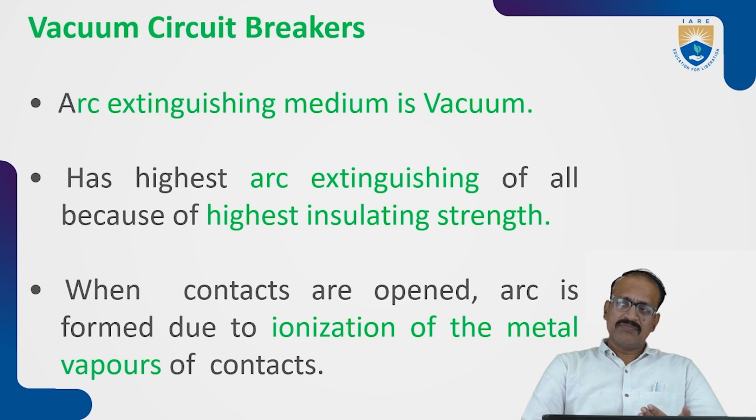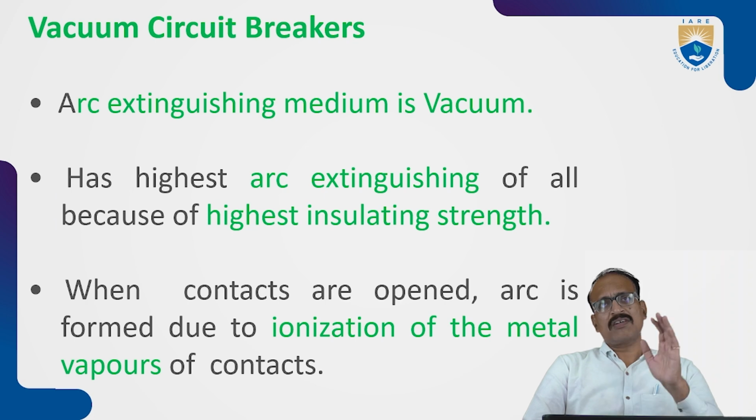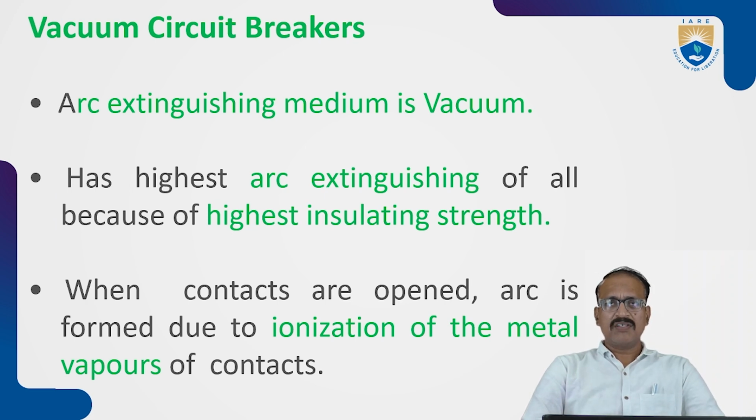Here the medium is the vacuum, and it is the best among all breakers because it has the highest arc extinguishing, because vacuum provides the highest insulation strength.